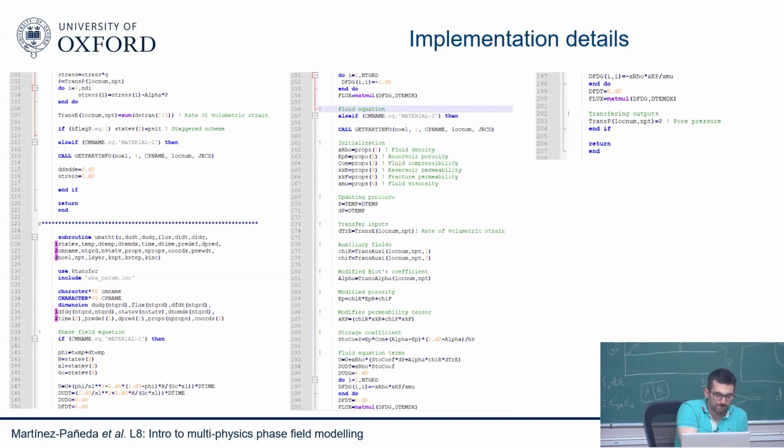Every time you solve a thermomechanical problem, Abaqus gives you the option of solving for displacements and temperature at the same time, or segregated, one and then the other one. Then you can tell Abaqus what to pick, and because you have two parts, you cannot solve all three field quantities at the same time, but you can solve two monolithically, one staggered, and the multipass. There are multiple options.